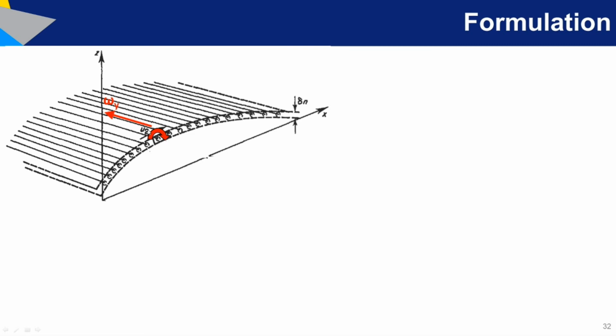That's the vorticity component along the span. And this is the velocity at which this vortex filament is advancing inside the boundary layer. So the cross product between this velocity and this local vorticity will give me locally a certain lamb vector component.